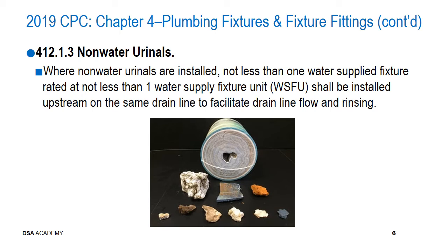It was determined that water is needed to clean the waste line from the non-water urinals that are in the horizontal position. And again, this keeps down on this sediment matter, which is called struvite. Okay, struvite is a mixture of various chemicals, including magnesium, ammonium, and phosphate. And it collects very quickly and solidifies in the drain piping leading away from the urinal.